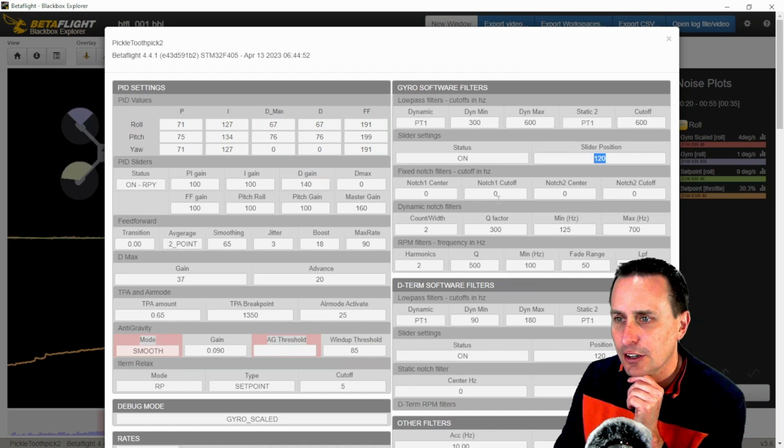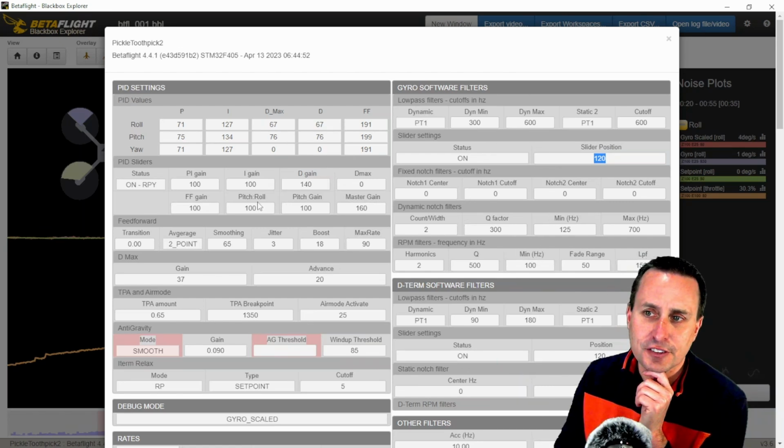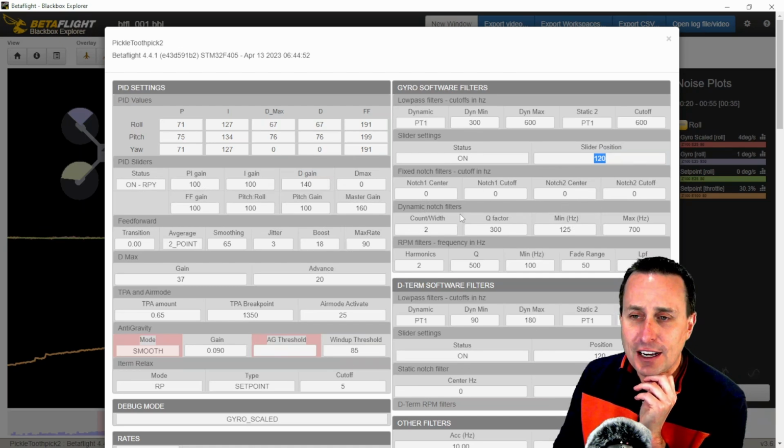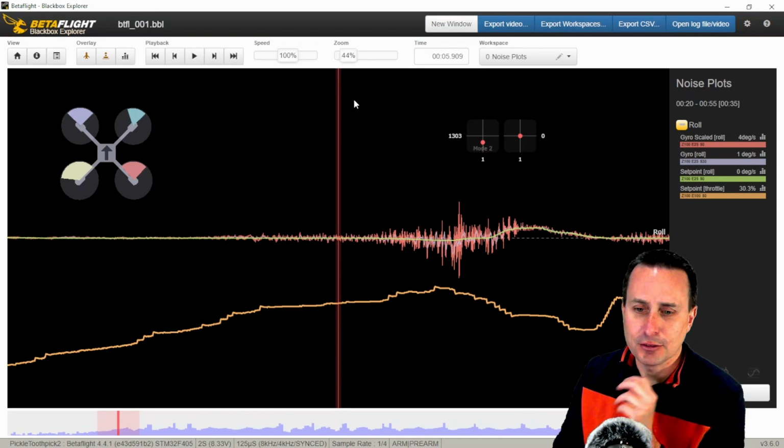Yeah, these look okay. At the end of the day, you can only lower these PIDs. You're never going to get these filters low enough to address stuff down at 50 hertz. You can't do that. The lowest you can do is like 80s for big rigs and stuff like that. So yeah, filters I think are fine. It's not that. I would lower these PIDs down. They're not helping it. Something's an issue there resonance-wise.